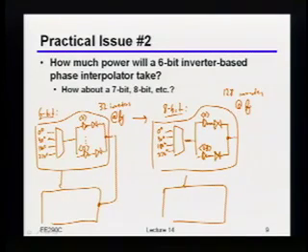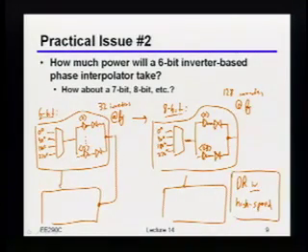Our big problem here is that all of our dynamic range is right in the high-speed signal path. That's exactly what you want to avoid. This is exactly what you don't want to have happen. Because anytime you need high speed and high dynamic range, that costs you power. No way around it. So indeed, it turns out that this particular way of building things is not very popular, because it couples the dynamic range you need with the high speed signal path.